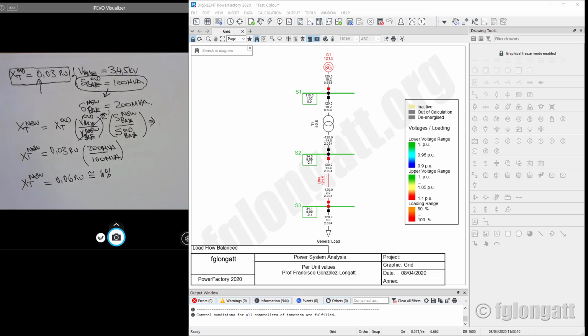You are installing a bigger transformer, but if you would like to keep the per unit values, you need to make the proper changes. And probably in the results you don't see any changes, and you will say, no, it's not affecting the results, it's just modifying the apparent power, and that's all. But that is not true. To be honest, that is far away from the reality, and you're making big mistakes.